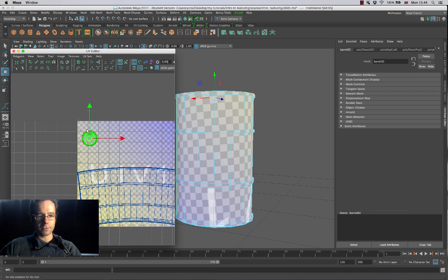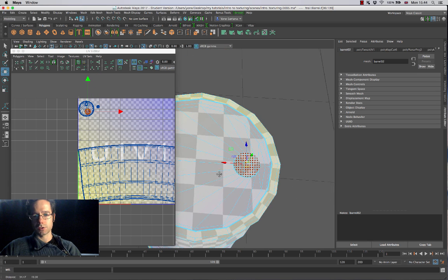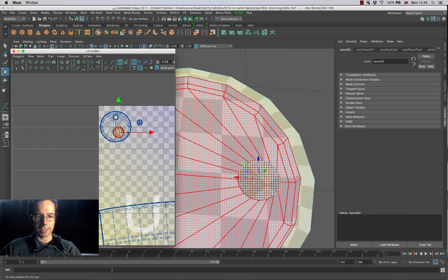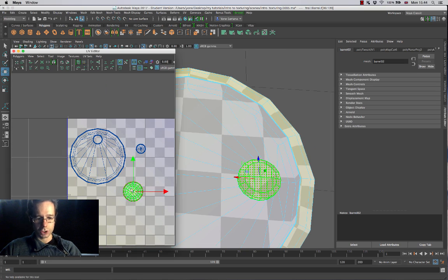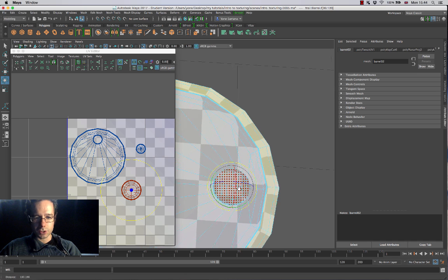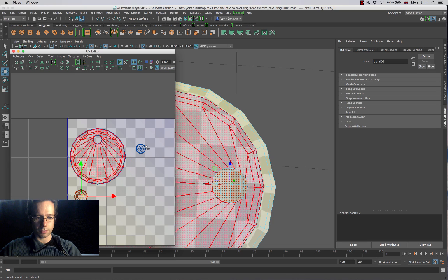So for example, if I come over here and I just start moving some of these shells around a little bit, just so that I can actually see what scale they have over here, we can repeat the same operations that we've been doing before of looking at the size of the little squares which are contained inside of these UV shells, and we can rotate them around and try to visually map them like this. And again, this is just about organizing how our UVs actually look, which the unfold tool has given us quite some easy UV shells to actually start playing around with.